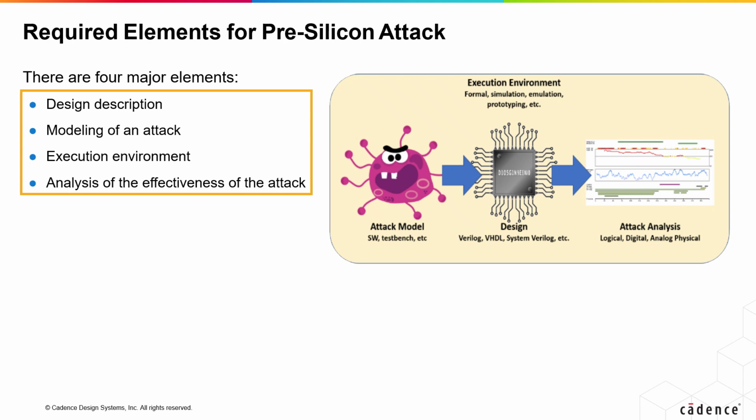For the fault injection attacks, we employ fault simulators, which were developed in-house, to inject faults into the design and analyze its behavior. This technique is also used in the automotive industry to test failure resiliency. After simulating various attack scenarios, we perform statistical analysis on the design's power consumption patterns to identify potential side channels. This analysis is based on well-documented algorithms, which help us detect anomalies and vulnerabilities in the design.